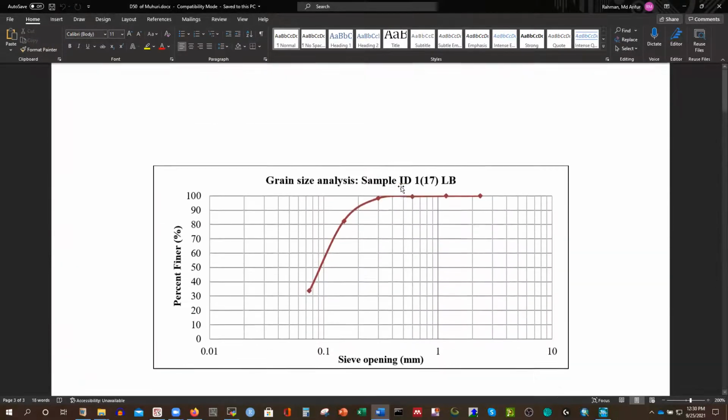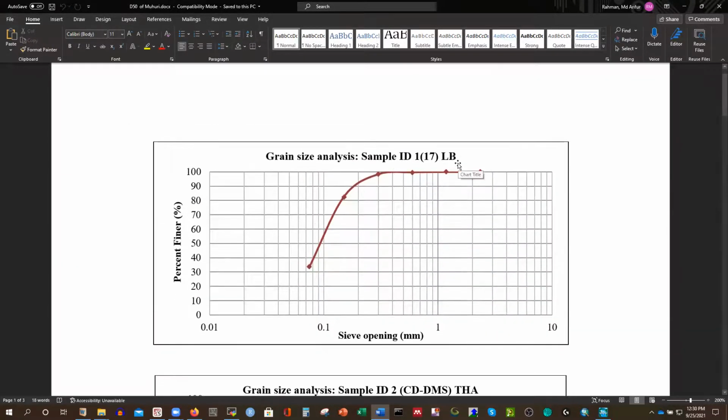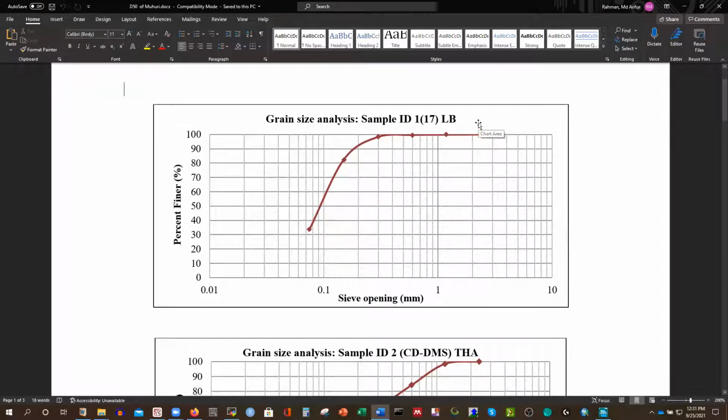This data has been collected by the same survey company we assigned for collecting the cross sections. They did it at the same time. They collected this material from the left bank, right bank, and just close to the bridges, because we have other bridges as well on the same river. So we tried to analyze the bed material and the distribution of the material as well.